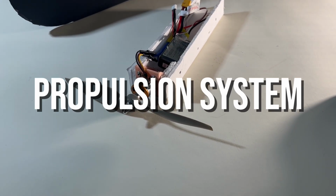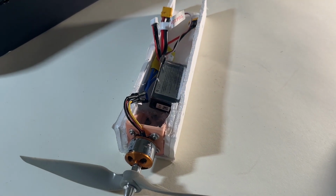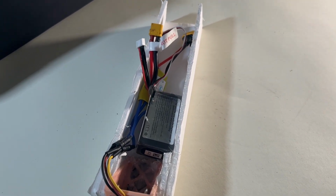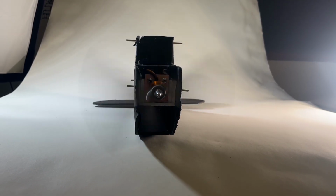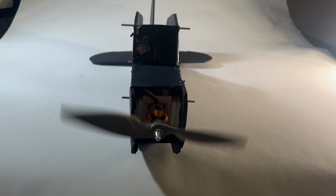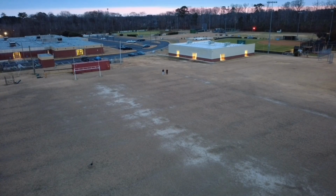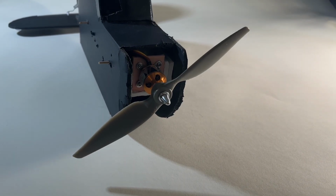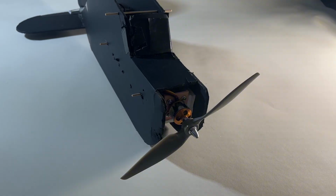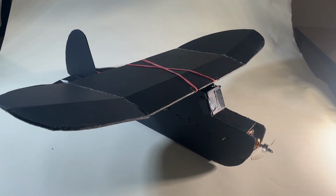Our propulsion system used a 1000 kV brushless motor paired with a 9x4.5 propeller, controlled by a standard electronic speed controller, or ESC. This setup provides steady thrust without forcing excessive speed, which matched our slow fly trainer style design approach. One major lesson we learned is that propulsion systems are especially vulnerable to damage. Even small impacts can bend a motor shaft, and once that happens, thrust drops significantly, even if the motor still runs. For our electronics and RC control system, we kept the setup simple and reliable.